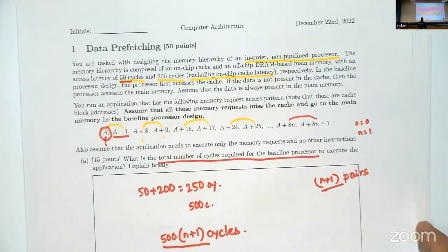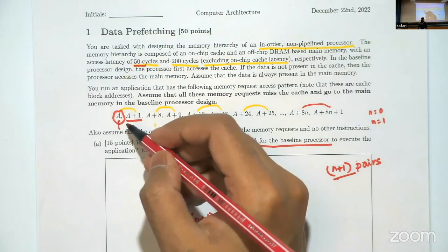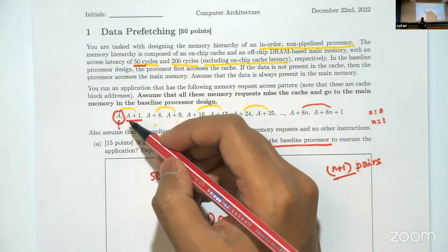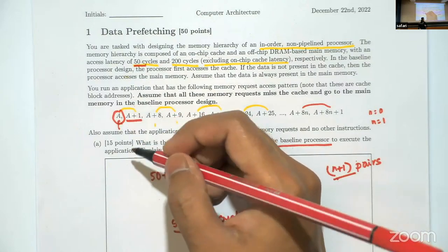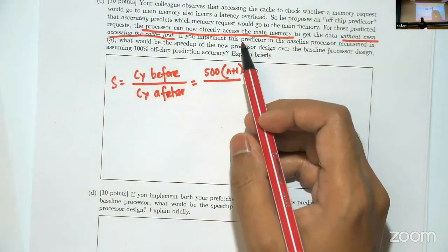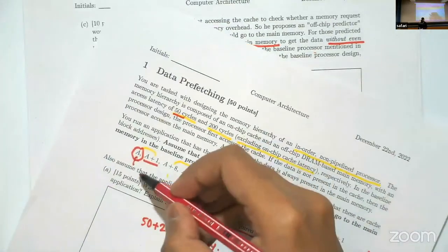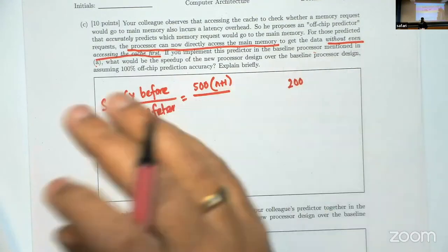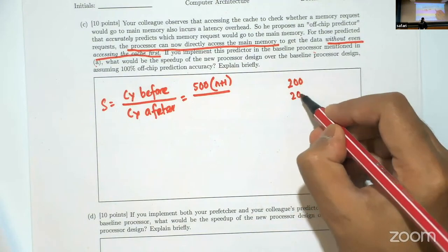So where were we? In this case, what would happen if we have the off-chip predictor? The first access would go to main memory, but instead of paying the entirety of 50 cycles plus 200 cycles, the off-chip predictor would predict accurately, as the question says, that it would go to main memory. So you would directly access the main memory without even accessing the cache. That means for the first request, you are going to need just 200 cycles. For the second request, because you are not paying the penalty of accessing the cache hierarchy, you would also need 200 cycles.